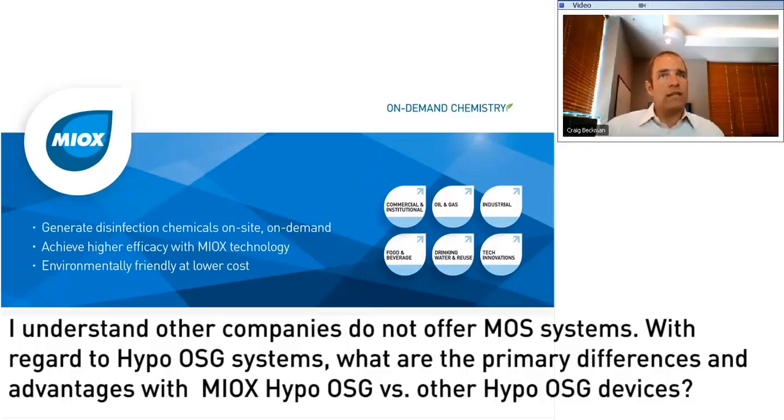Again, the differences between the mixed oxidant chemistry and the sodium hypochlorite is the design of the cell. We run the cells differently. We do some other things differently that I can't share, but it is a different design cell. And so if you were to buy a Rio unit, you need to specify up front if you want a mixed oxidant unit or a sodium hypochlorite unit, and you do also give up some capacity. So you give up about 20 or 30% output by volume when we make the mixed oxidant. And so that is a trade-off between the two chemistries.